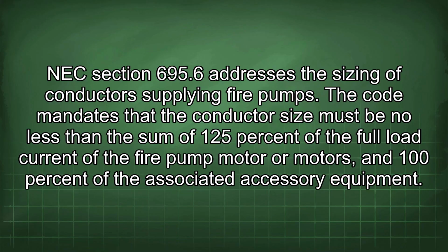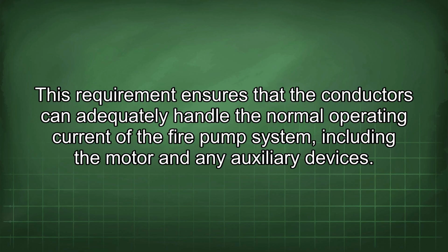NEC section 695.6 addresses the sizing of conductors supplying fire pumps. The code mandates that the conductor size must be no less than the sum of 125% of the full load current of the fire pump motor or motors and 100% of the associated accessory equipment. This requirement ensures that the conductors can adequately handle the normal operating current of the fire pump system, including the motor and any auxiliary devices.